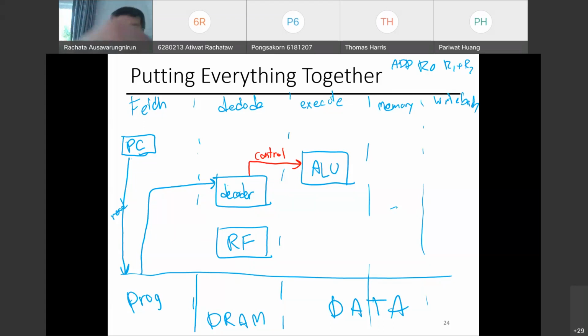So what else do I have to do? Select R1, select R2. I will say, hey, I want R1 and I want R2. In this case, the register file has 2 input ports to read. Okay, I want R1 and I want R2. With me so far? Let's say I want to do just an add, right? So this control would be add. Okay, what's next? Now I've figured out the add, I gather the operands, right? So this is basically where I gather the operands.